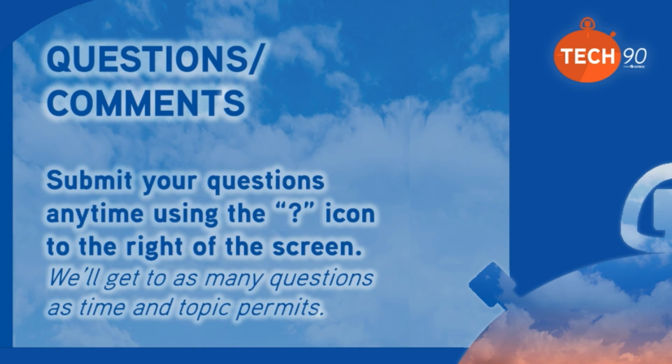The other thing you could do, if some of you are doing any multi-zone mini splits for GREE, is that a lot of the multi-zones come with adapters, because you size your line set to the indoor unit, and then you reduce it down to connect to the outdoor unit.